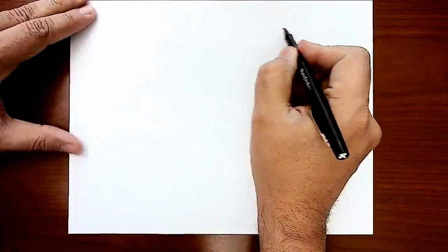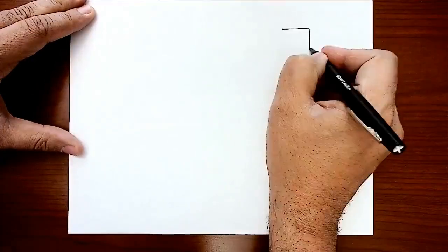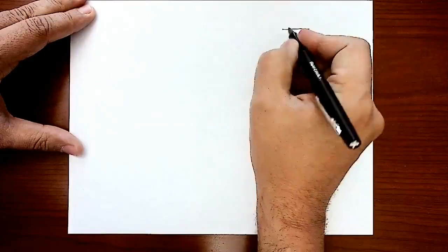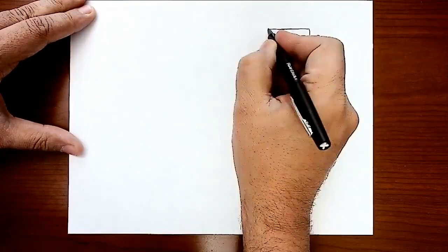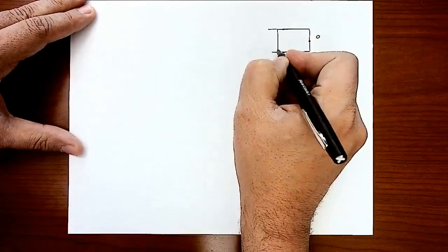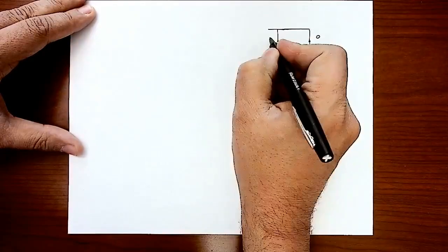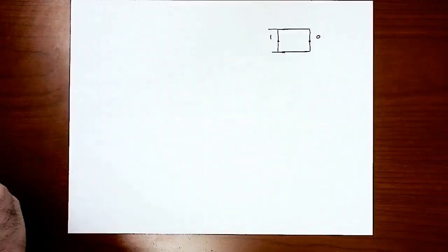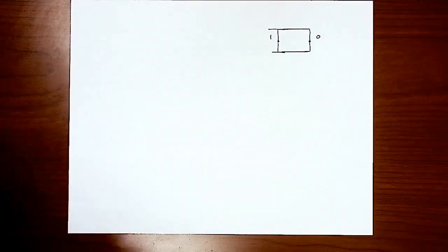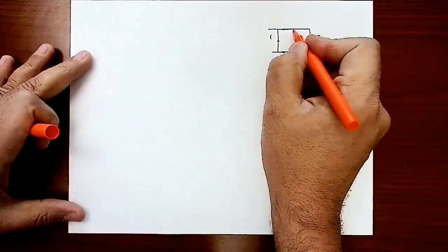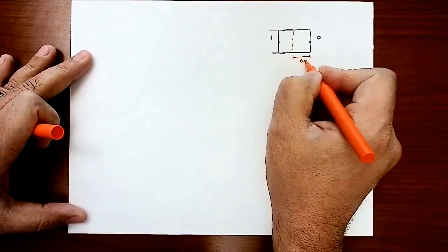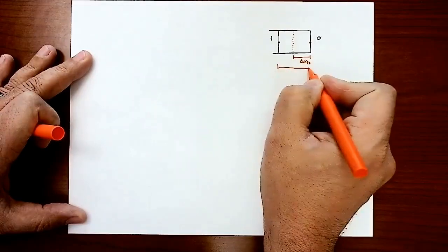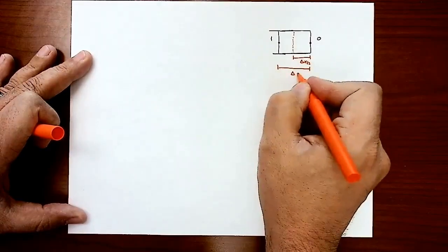So what about node 0, right? Node 0 is on the right side of the problem, the right boundary condition. This is node 0. Then I should have node 1 in here. Now, if you draw the control element, you should have that line here over a distance here that's delta x over 2. The overall distance between the two nodes is delta x.